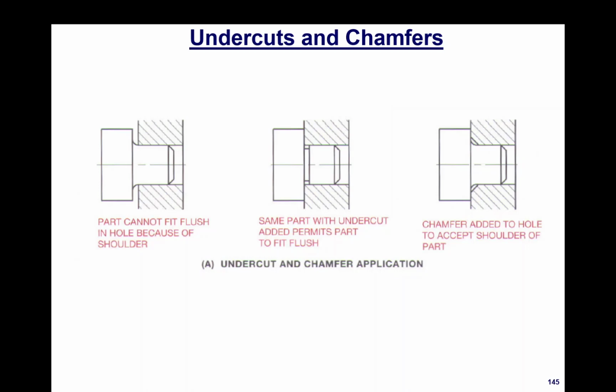It's called a shrink fit. So when we use a press to force these two components together, having this angled or chamfered edge on the shaft allows for piloting and alignment, so that we can force these components together. So that's another application of the chamfer. Okay.